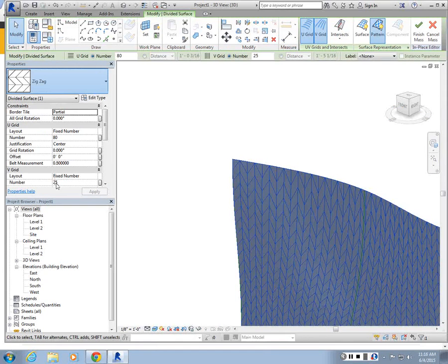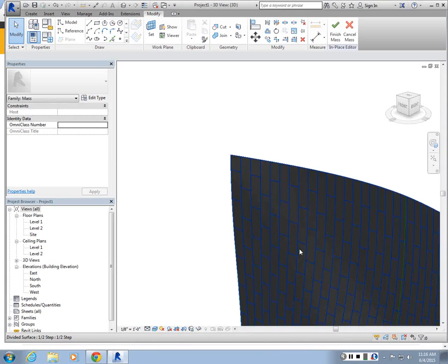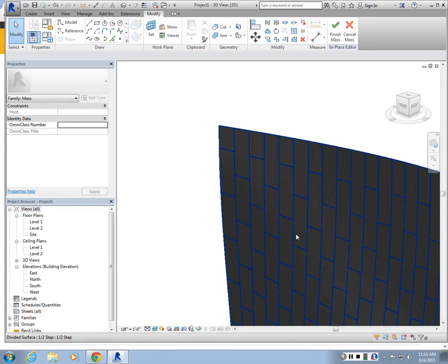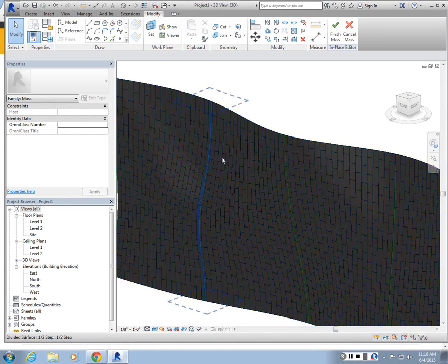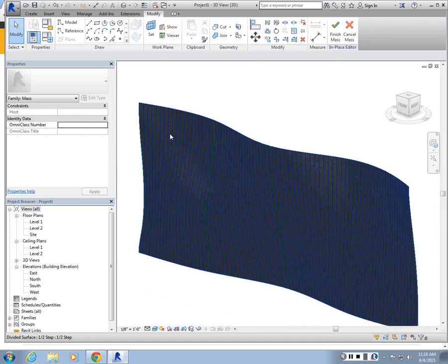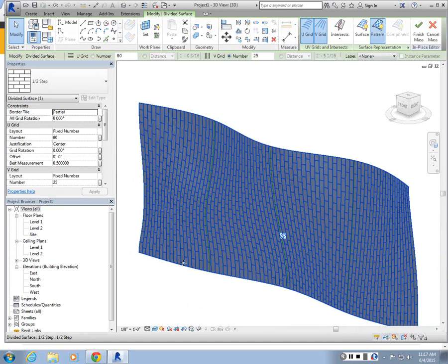So let's make one. The one that I like using is the 1-2 step, because it can create really shifting, tilted panels and patterns. Sometimes it looks really nice. So I'm going to make a family and bring it here and use it for this type of division.